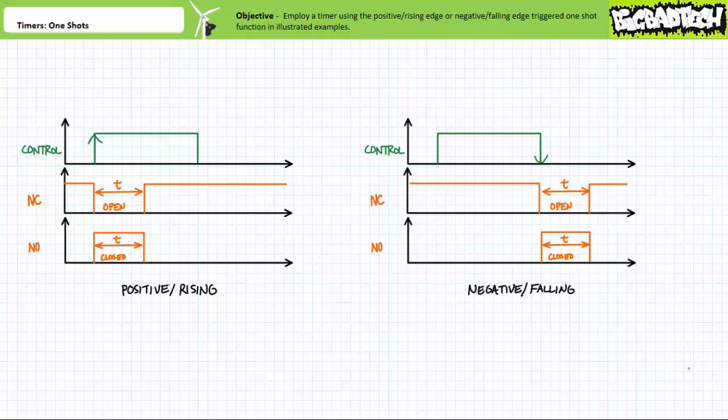Being solid-state devices, the microchip conducting the timing operation often needs to be continuously powered up for it to execute the one-shot function, especially in the case of negative edge-triggered one-shots. The internal circuitry of the microchip would be responsible for keeping the associated contacts in their opposite state for the required delay period after the controlling input disappears.